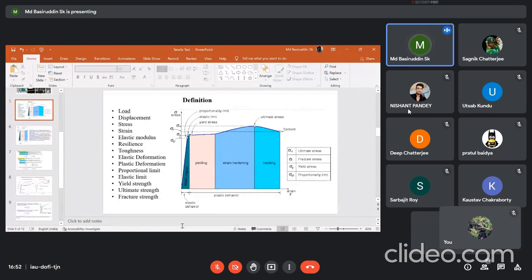Let's say if we want to calculate the ultimate tensile stress, and if we know the load, then how can we calculate that? From the basic stress equation, we know that stress is load divided by area, right? So in engineering stress calculations, if we know the maximum load and divide it by the gauge cross-sectional area, then we will get the ultimate tensile stress, right?